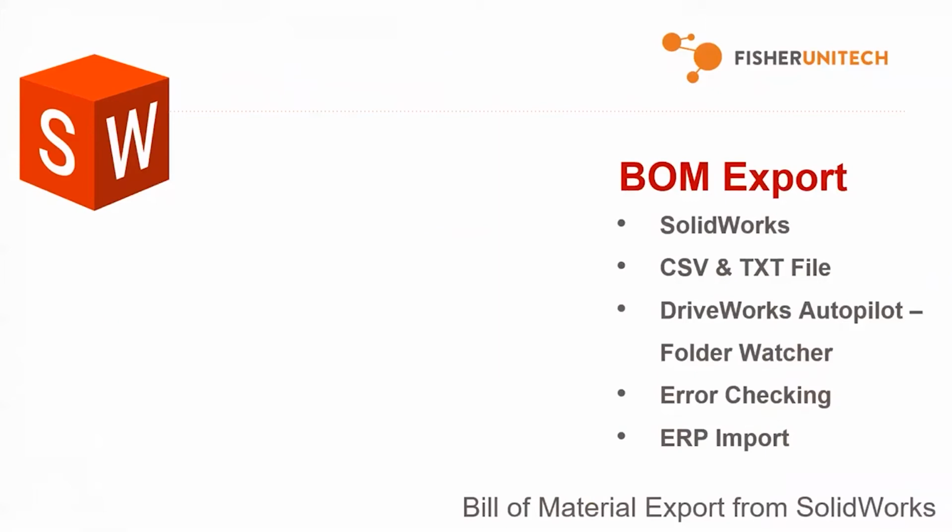And what we've discovered here is, by piecing together a couple of chain of events here, leveraging DriveWorks Autopilot and this folder watcher capability, leveraging some of our integration tools that we had for our ERP system, right from creating stuff right out of SolidWorks, we've been able to, from the SolidWorks interface itself, push our bill of materials into our ERP system. Typically in the past, this process would take probably 3 or 4 minutes if everything went smoothly. If there were problems, which happened with a fair amount of frequency, it would often take a lot longer than that.